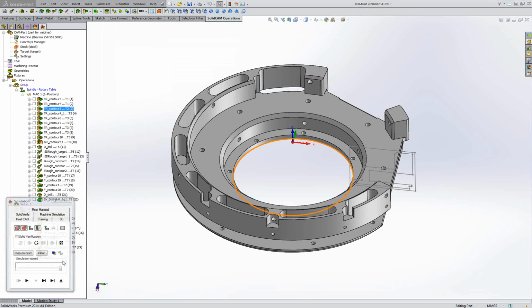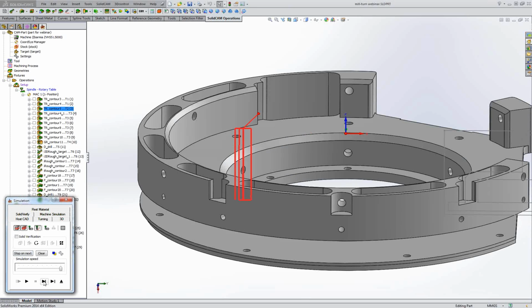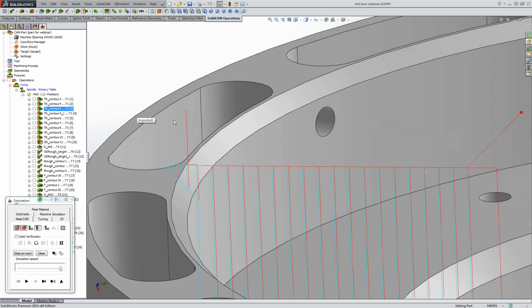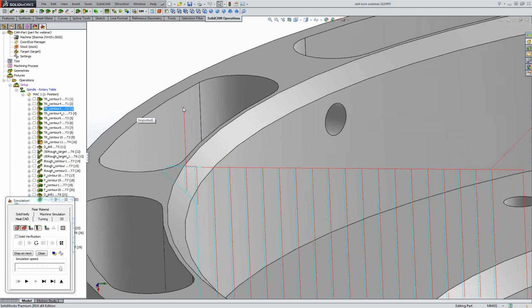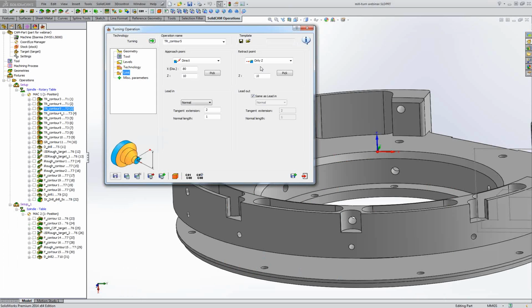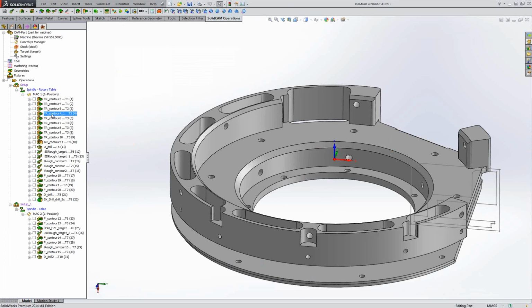As we define in the job, from approach point go direct to start of toolpath, and all the rough operation, all steps. Last movement is only Z to 10 millimeters retract. That's exactly what we define. Now I remove the material on face, outside, inside, rough. Now I will start to define the finish operations.